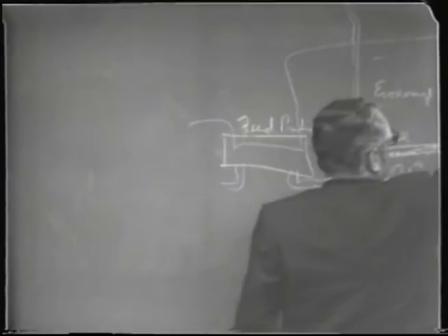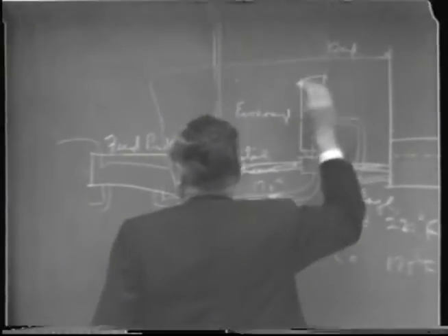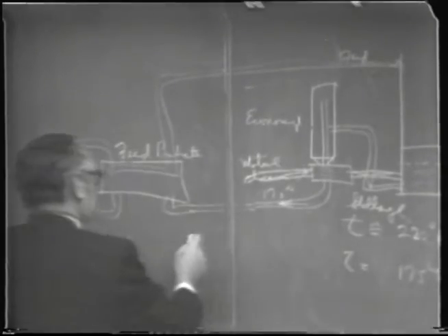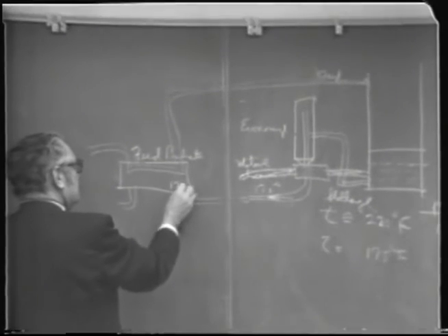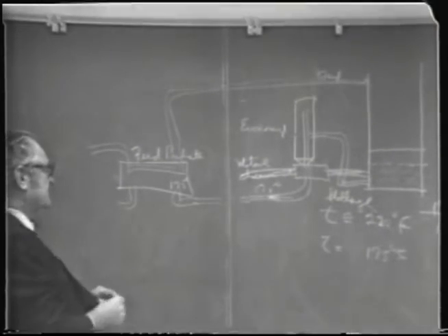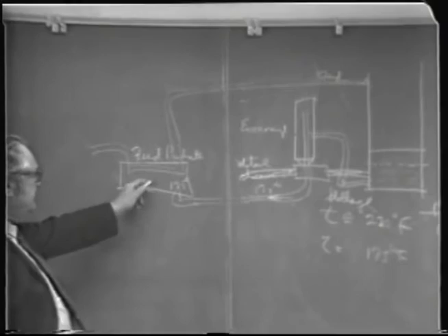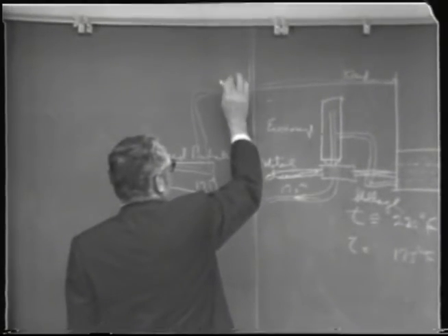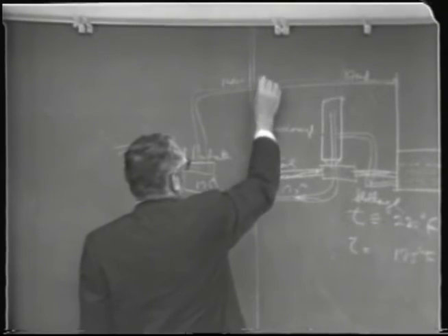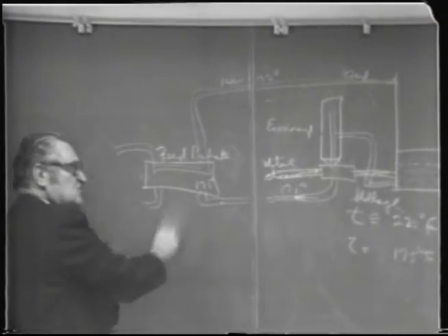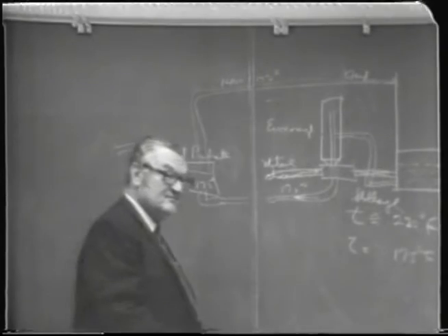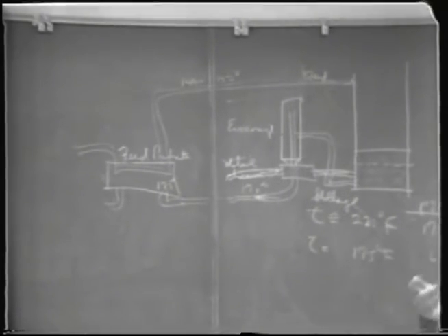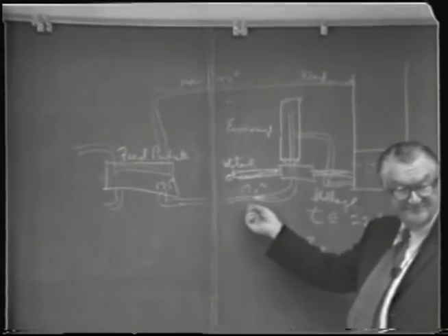The feed goes in up here. So if this goes in at only 175, and we want to get, let's say, 140 to 150 degrees out of that, we can't have it much lower than that, or we won't have any preheat available. I won't have the opportunity for preheating the liquid. So not much point in dropping below that, even if we could.